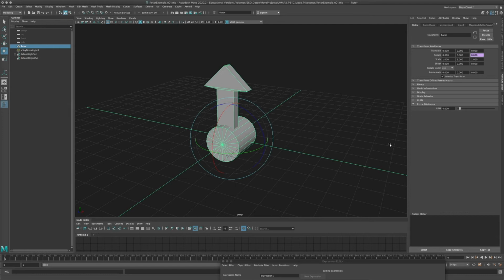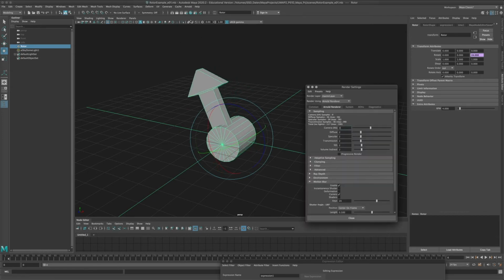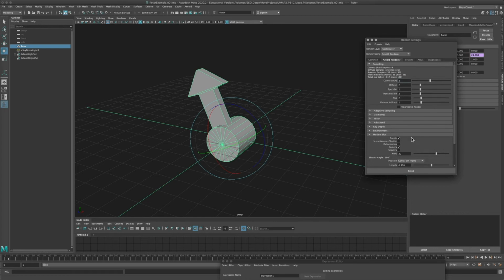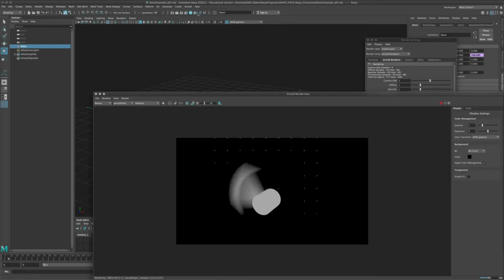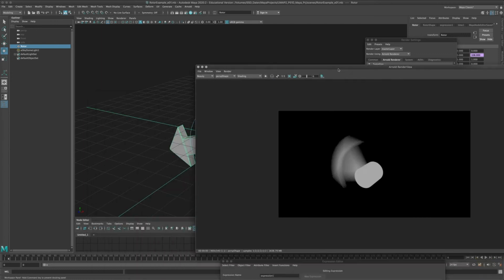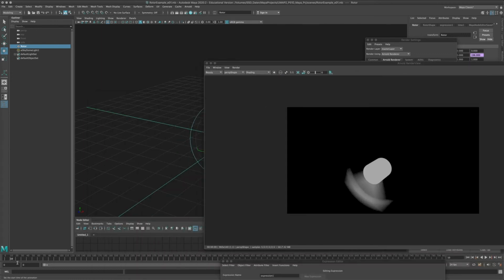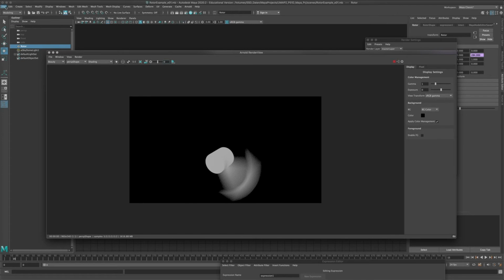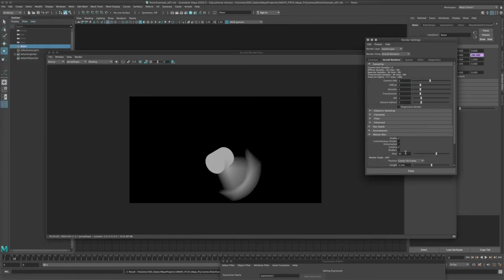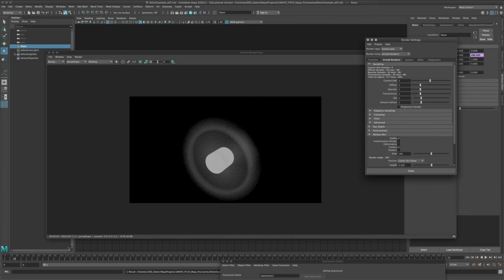I'm going to reset here. So we're adding 4 every frame. Let's check again. I wouldn't need it right now, but let's keep it on 20 time steps. Let's press render and see what happened. Let's move forward again and take a look at the little time slider right here. It's pulling 20 motion steps between frames. Let me make that even more apparent and put that to 100. See what happens? The motion blur completely changed.